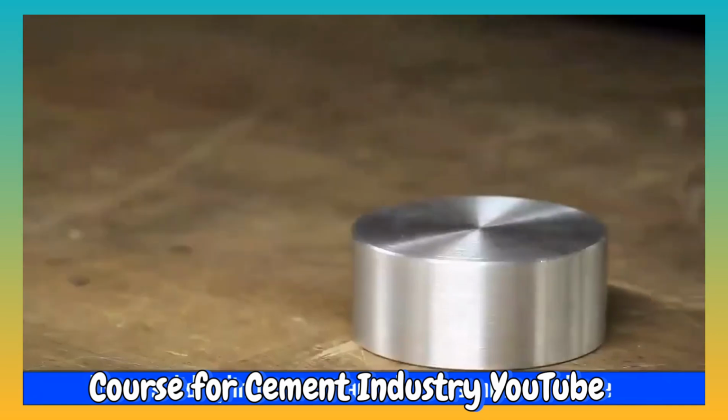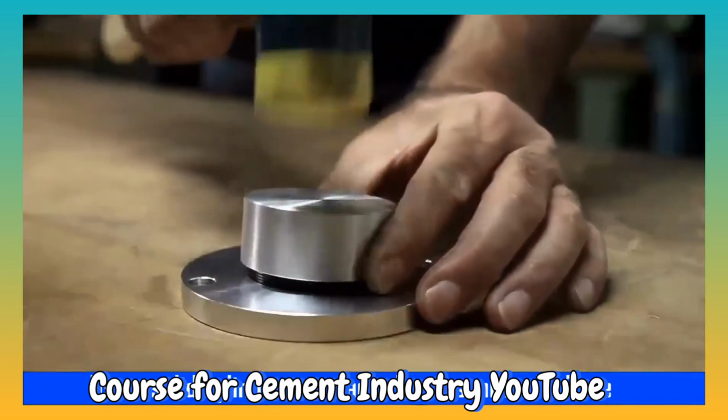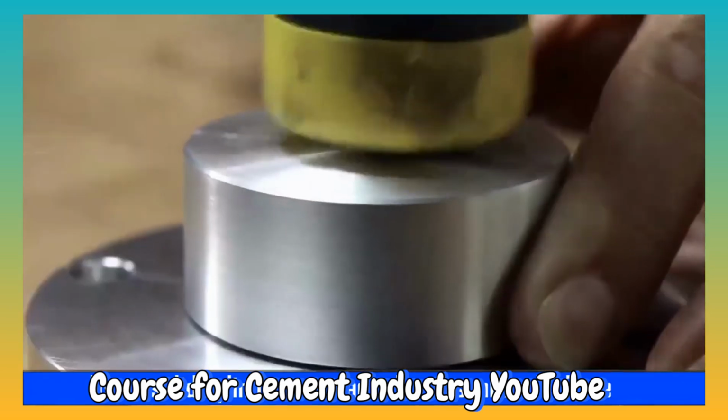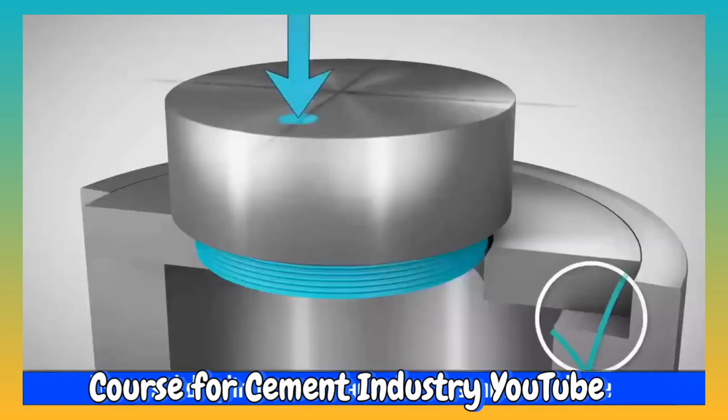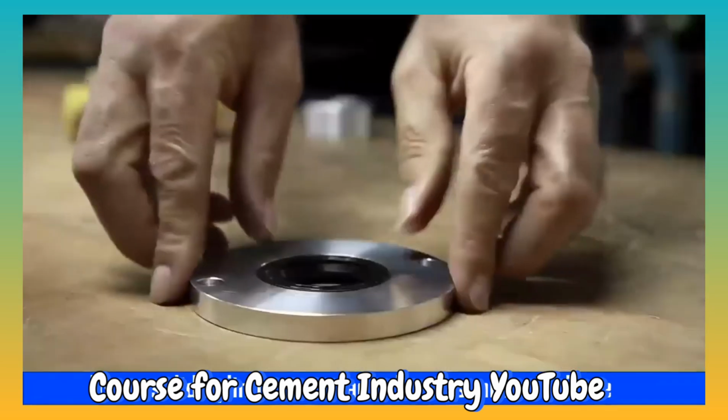Use a solid cylinder to attach the oil seal to the bore. When hitting with the hammer, alternate crosswise so that the pressure is evenly distributed.